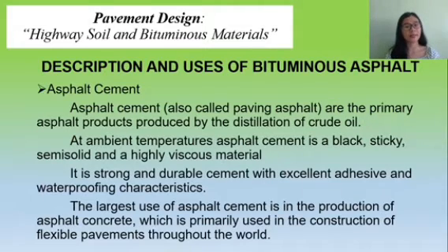Asphalt cement, also called paving asphalt, is the primary asphalt product produced by distillation of crude oil. At ambient temperatures, asphalt cement is a black, sticky, semi-solid and highly viscous material. It is also a strong and durable cement with excellent adhesive and waterproofing characteristics. The largest use of asphalt cement is in the production of asphalt concrete, which is primarily used in the construction of flexible pavement throughout the world.